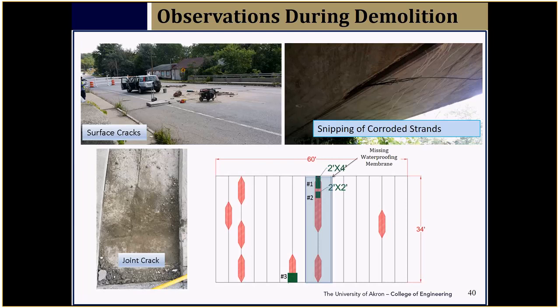Even the membrane itself, the heat alone of the asphalt, any air that's trapped in the waterproofing is just trying to expand. And I think that's pretty difficult to construct. That's kind of why I asked that question. I'm not saying... Yeah. We don't put a waterproofing membrane underneath concrete. That's right. And right now, our policy is the